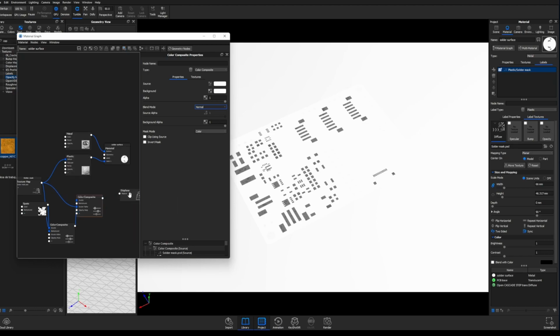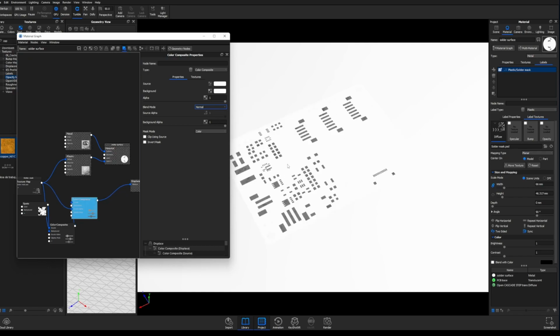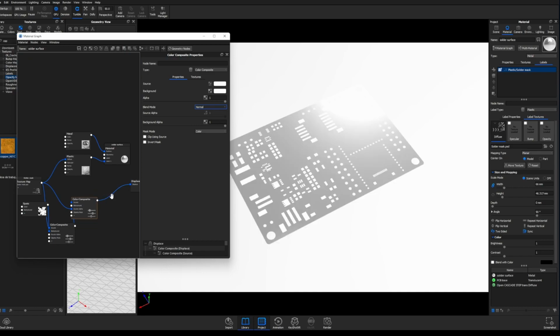Yeah, because I want this to make that extrusions, and I'm gonna click now into utilities, sorry, geometry, displace, so I can execute a displacement node. I'm gonna connect it, but all the white areas are gonna be extruded the value that I set in the displacement node, and all the dark areas will be not extruded that much. So black areas will not be extruded. So in order to change that, because otherwise this white area will be extruded, I can select this node, this connection, right click on it, utilities, and color invert.